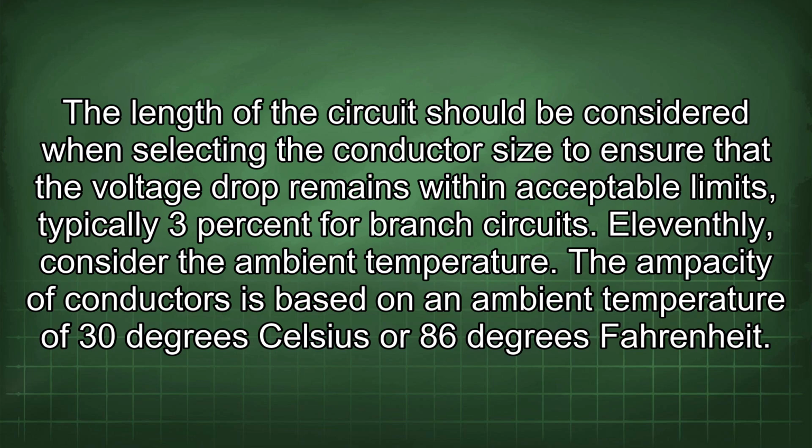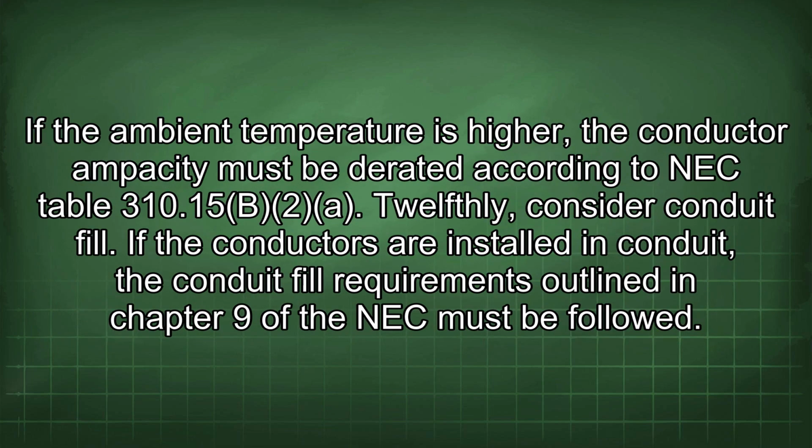11thly, consider the ambient temperature. The ampacity of conductors is based on an ambient temperature of 30 degrees Celsius or 86 degrees Fahrenheit. If the ambient temperature is high, the conductor ampacity must be derated according to NEC Table 310.15(B)(2). 12th, consider conduit fill. If the conductors are installed in conduit, the conduit fill requirements outlined in Chapter 9 of the NEC must be followed.